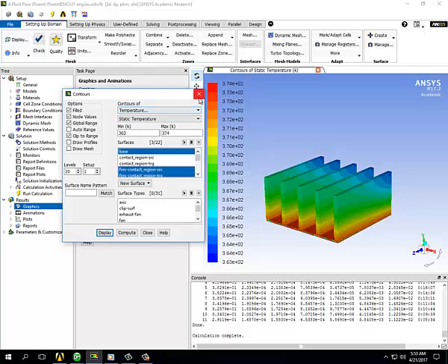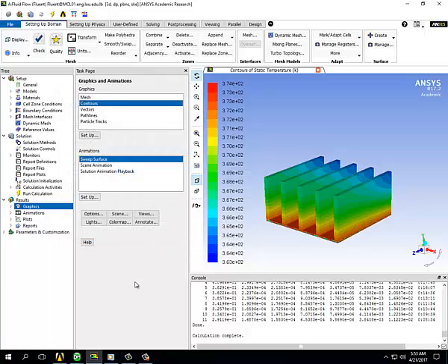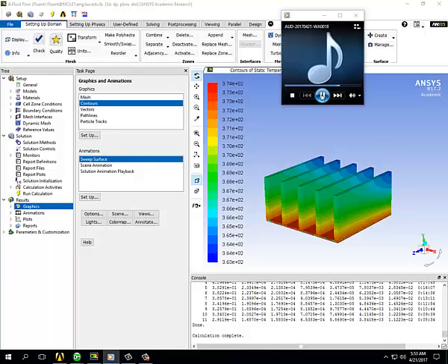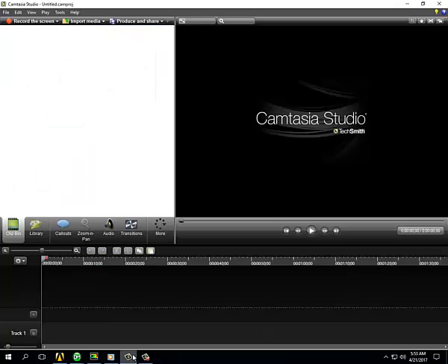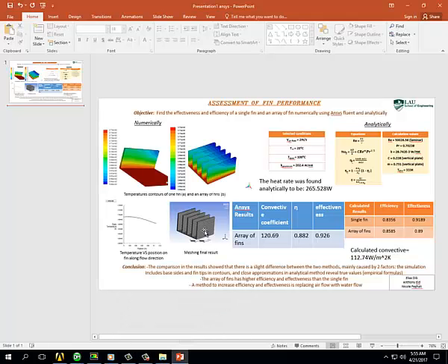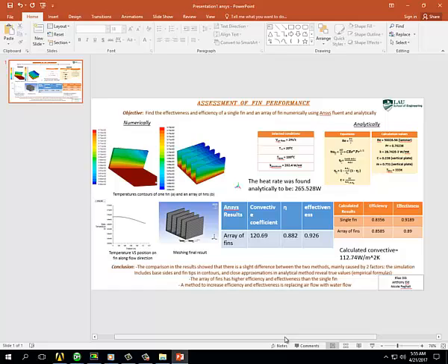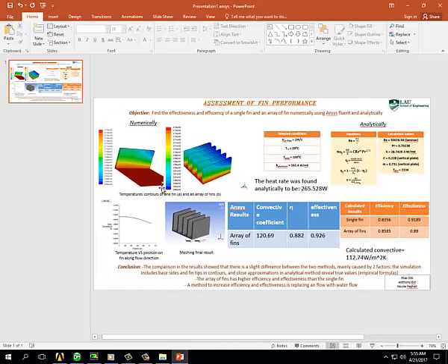After that, we can check our PowerPoint. This is going to be our mission. Over here we can see we can compare the single fin to the multi-fin. Also, we have the temperature distribution versus position. As we can see, it decreases as position increases. This temperature distribution was placed on the center of the fin, that is at 0.0025 meters, or 2.5 millimeters, of thickness in the fin.